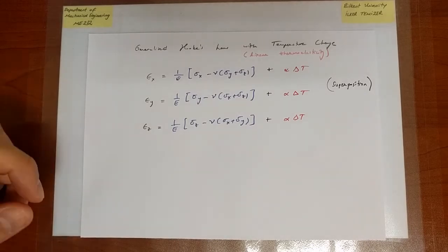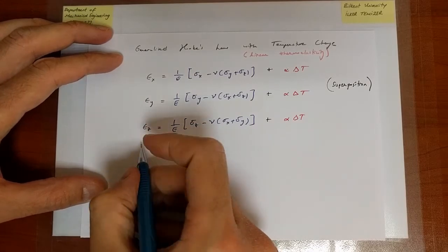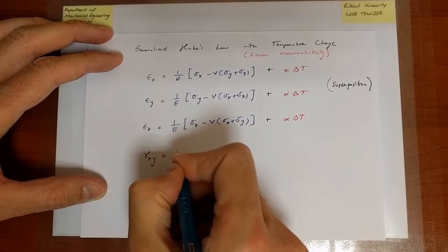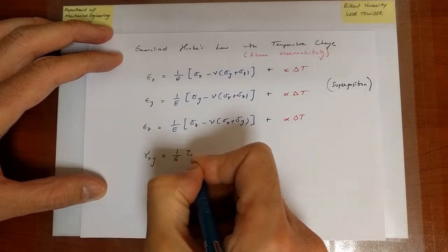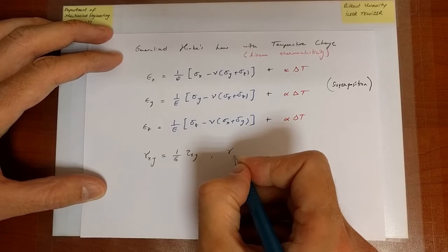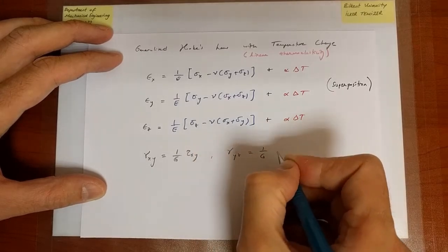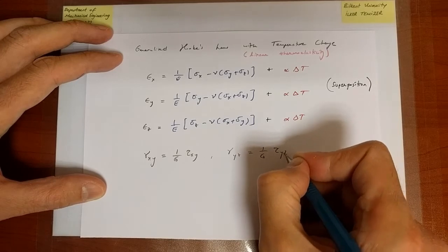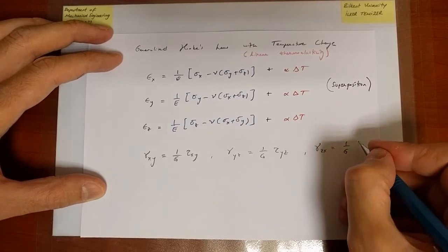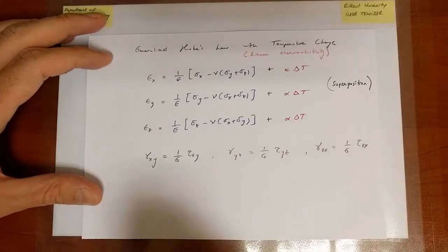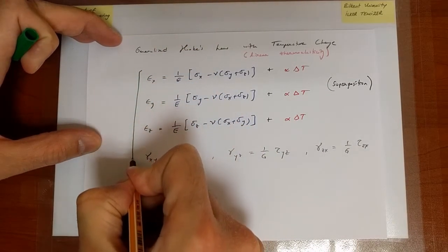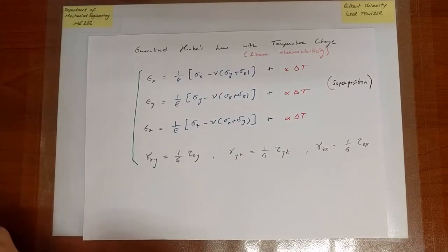Good. So, well, let's recall what happens in the case of shear strains. Well, for shear strains, I already know that the relations are somewhat simpler. We have the expressions that relate a given shear strain to a given shear stress. And now, moreover, we know from our experimental observations that there is not going to be any thermal strain contribution to shear strains. Okay, so those are the shear strains still. And therefore, this is now our generalized Hooke's law with temperature change.